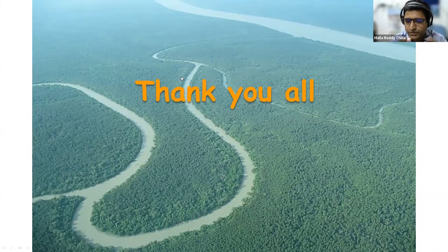But I would expect that these crystals may not show complete recovery in terms of mechanical strength, because we see that when you poke a crystal at different locations, once you have a crack in one place, although it shows that it is healing completely, it actually cracks at the same place, irrespective of where exactly you poke it. So that tells that that is actually the weakest plane in the crystal, and that tells that this is not 100% healing definitely. But that would be interesting. There are some difficulties to do it because these crystals are not very big, and I think we have not spent much time on that. We are going to actually look at some of those.